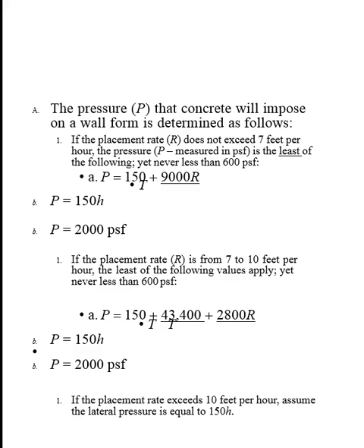Again, remember why they vary: the higher the wall, the more concrete, so there's more weight obviously, but the time between placing concrete at the bottom and the top is substantial, especially as the wall gets higher and higher. But that also means that the concrete at the bottom starts hardening, changes to just a straight dead load down, and there's less fluid load bearing against your wall. But you can see by having the 600 PSF minimum, you always have a guarantee of where you can go. If you can do some less based upon what you're designing, that's fine. Or if you're going to have more, I'm sorry, it's just the opposite of what I just said. You're always going to have at least 600 PSF.